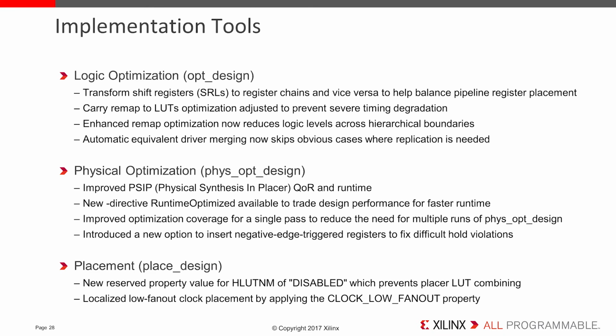For implementation tools, here are the major highlights of the main features. In logic optimization, opt_design now provides fine-grained conversion between SRLs and registers for flexible pipeline register implementation in high-speed designs. The carry remap optimization now only converts single carry chains by default to avoid massive timing failures while still maintaining fine-grained control. The remap optimization now works across logical hierarchy to further reduce logic levels.